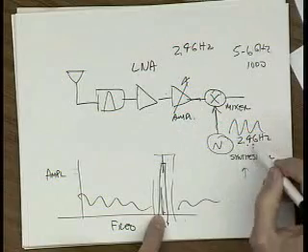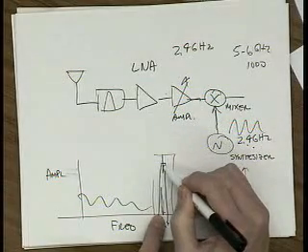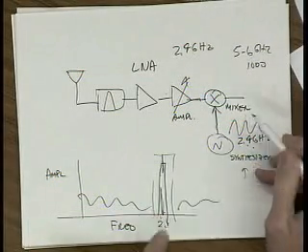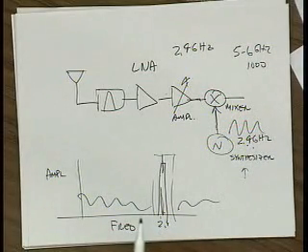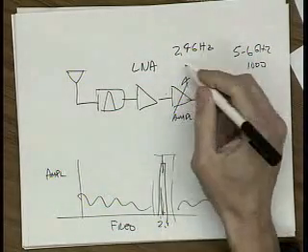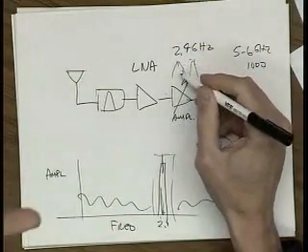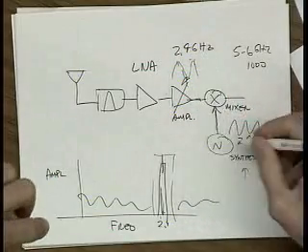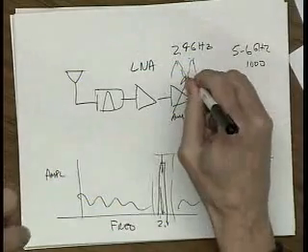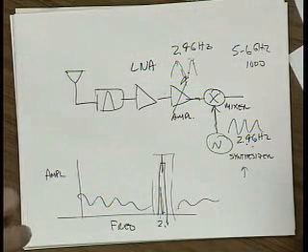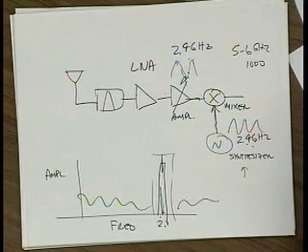You multiply this 2.4 gigahertz times your signal, and what do you get out? If you multiply two sine waves together, let's say the signal coming in here is primarily a sine wave with some sort of modulation on it, amplitude or phase modulation or frequency modulation. But if you multiply a 2.4 gigahertz signal times another 2.4 gigahertz signal, what do you get out? Two signals, two frequencies. What two frequencies? You get the sum and difference frequencies out, right?